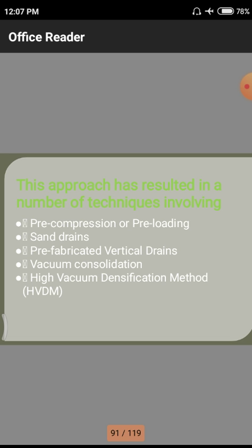That means sand drains are sandy materials filled in particular columns, so that the sand will have a capacity of bulking by absorbing whatever water is surrounding it, so that the total amount of water will be absorbed by these sand drains and drained. Next one is the prefabricated vertical drains.